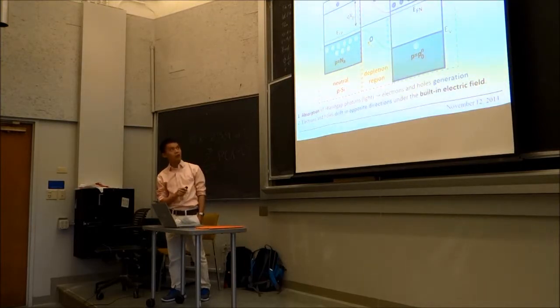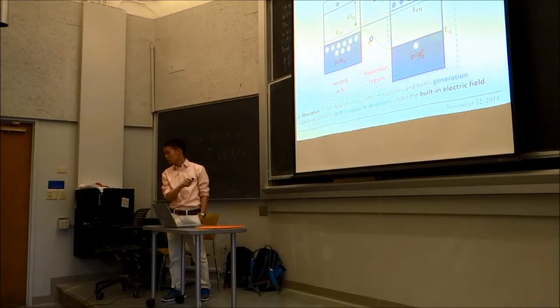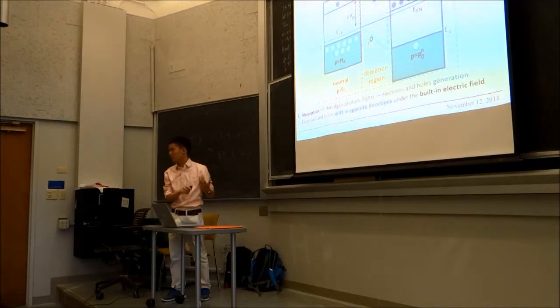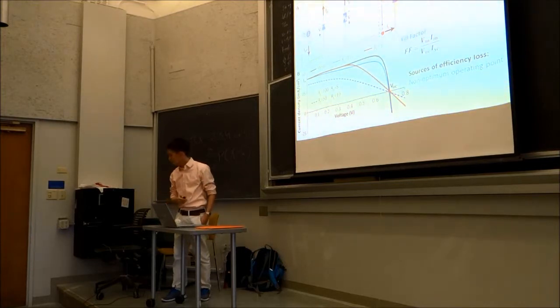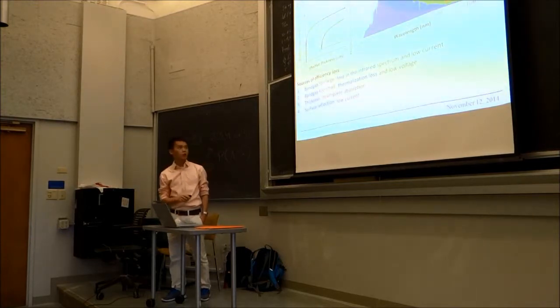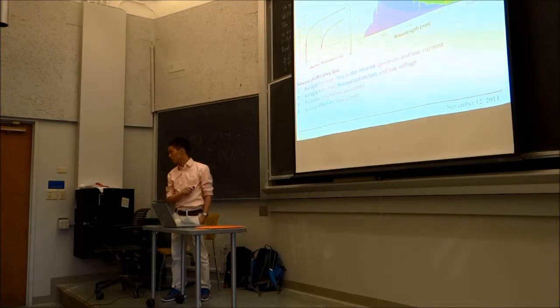What I'm talking about is that if you have a smaller band gap between the conduction band and the valence band, the open circuit voltage you can establish will be proportionally lower as well. So a lower band gap material gives a lower open circuit voltage, and lower voltage also leads to lower efficiency. So there is a trade-off there.